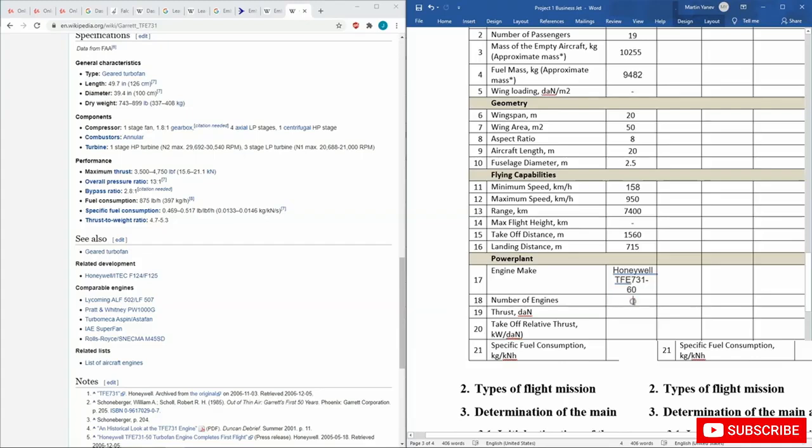But first of all, let's record the number of engines, and this aircraft has 3 engines. The takeoff thrust, I calculated it in decanewtons, so it was about 6,672. And then the takeoff relative thrust was about 0.32. And the specific fuel consumption I couldn't find for that engine.